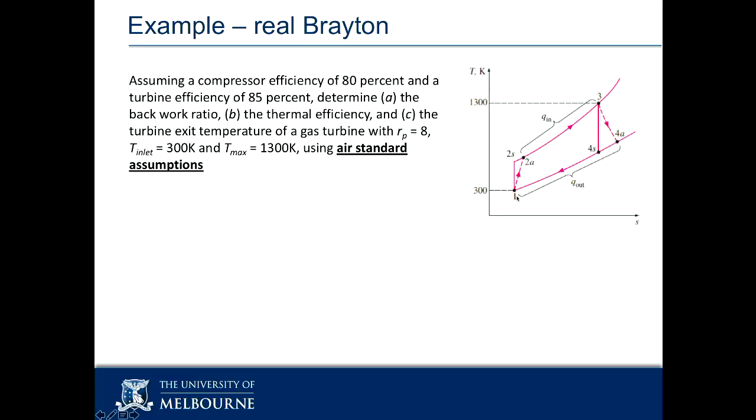So if I put both of those together, if I have a slightly inefficient compressor, I start this journey at a higher temperature, then I add my fuel temperature up to here, and then I have a slightly inefficient turbine, and then I release my heat out there. So as an overall result of the net work out, I have less work out of here, I did more work here, my efficiency has dropped because of the inefficiencies of the components in the machine. You follow that last step?